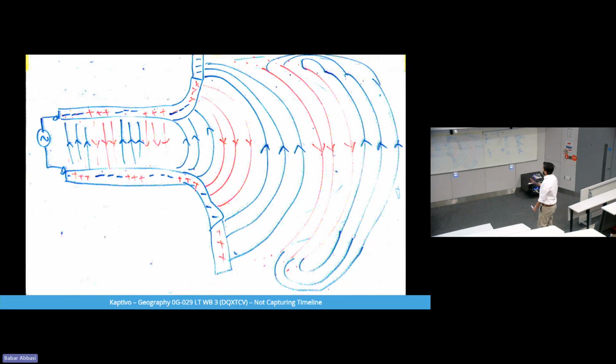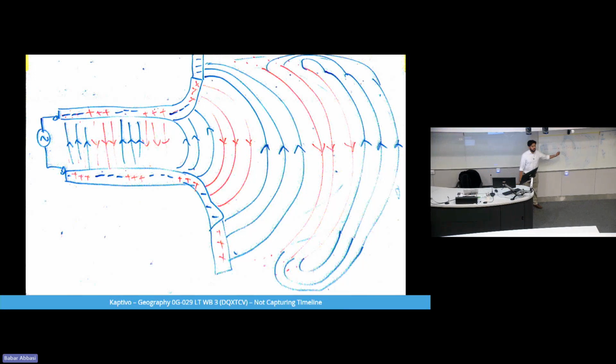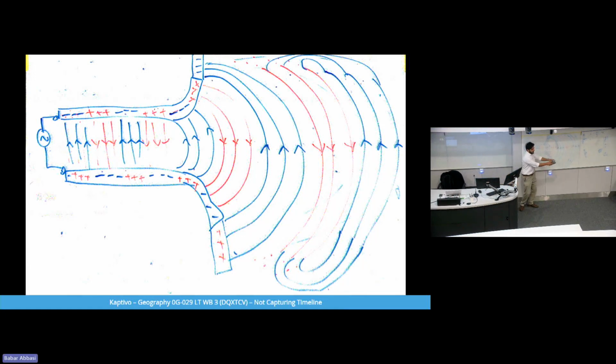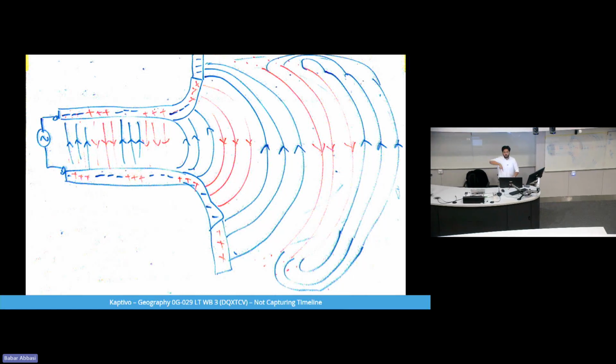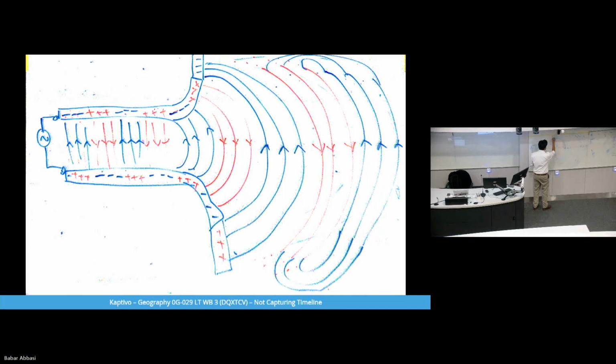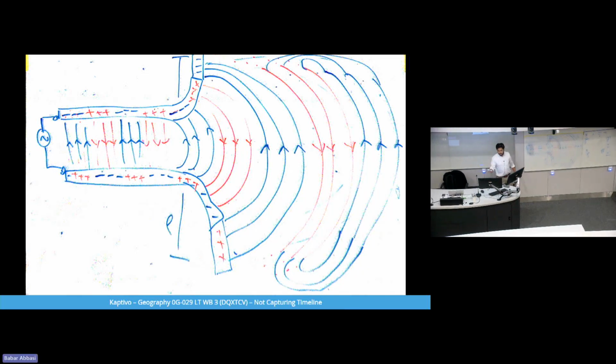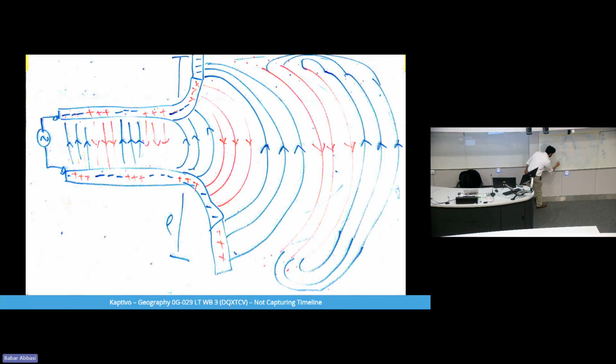So this is how a simple dipole is built. A simple dipole is basically an alternating voltage source connected to a transmission line, and that transmission line has an opening, and it has a structure like two strips. Important thing is this needs to be a particular length, L. And for our own understanding, we generally consider this L to be half wavelength, lambda by 2, because half wavelength is a nice number for us to understand what's going on.